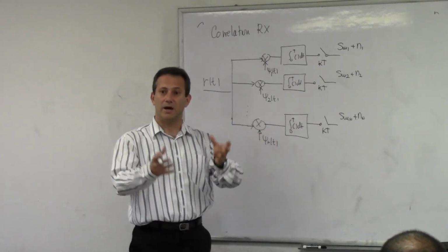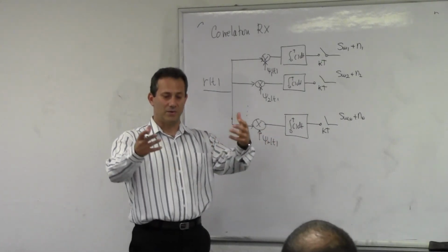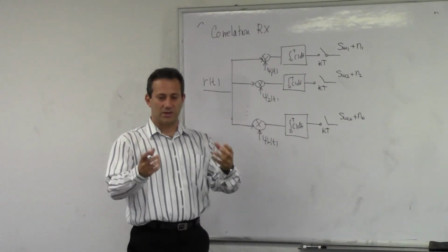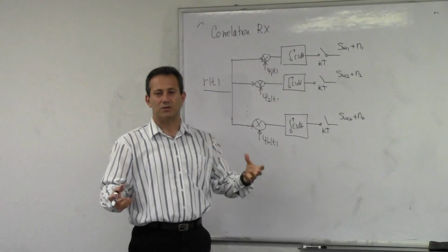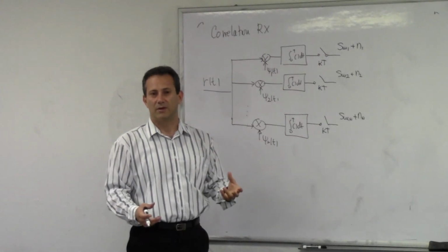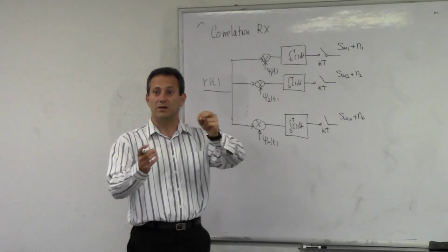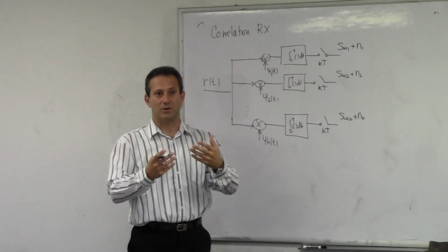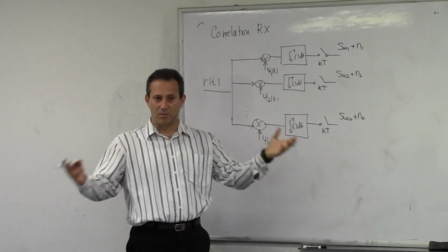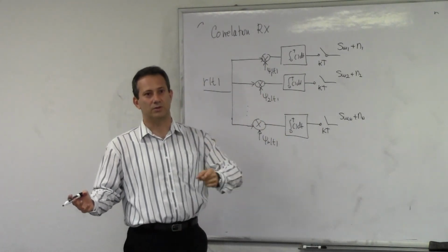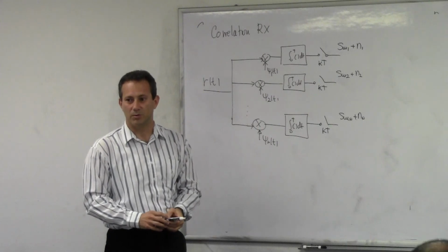We signal by combining the basis vectors, and we demodulate by looking at, in your signal, what portion of each of the basis vectors you have. And that goes back to my analogy, creating colors. You mix 3 colors. If I want to recognize what has been sent, I decompose along the colors, and I see what portion is red, what portion is green, what portion is blue.